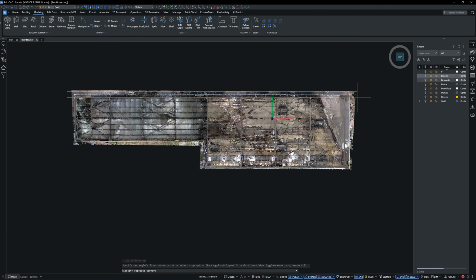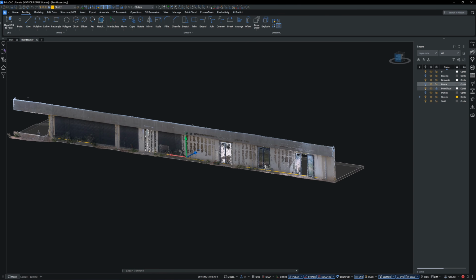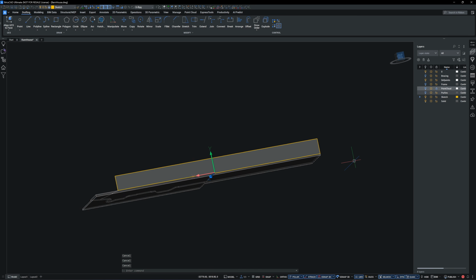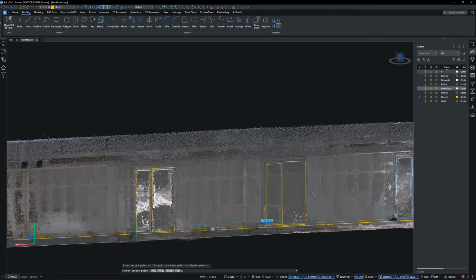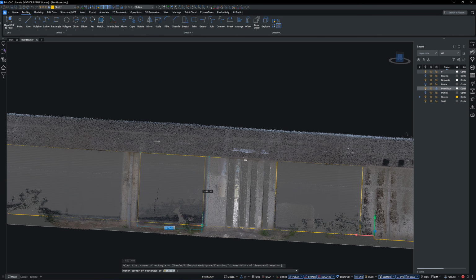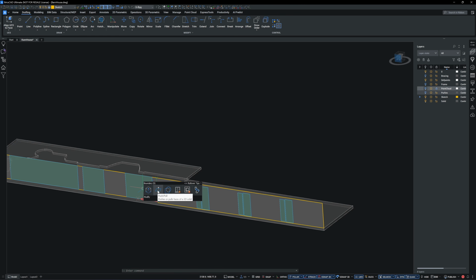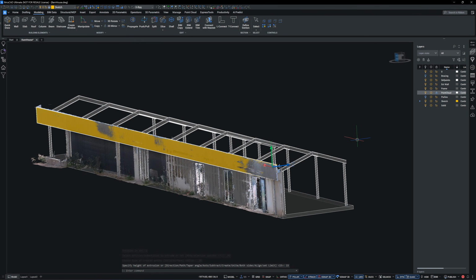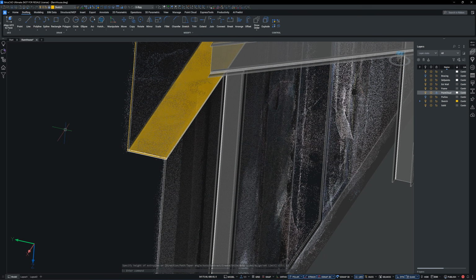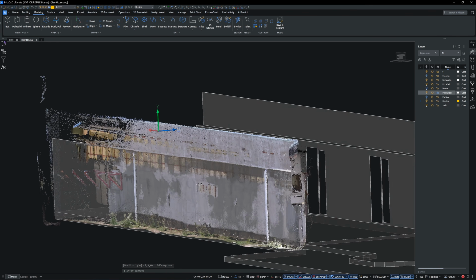Now I'm adding purlins. Purlins are used to support the roof cladding, in this case a metal sheeting with a spacing of 1 meter. The steel profiles most commonly used for purlins are C-shape, light lip channels, or U-shape sections. Now I'm adding drywall panels and cutting out the door opening. This panel is used to conceal the metal roof sheeting and the rain gutter from view. It's a common practice in commercial and industrial buildings.